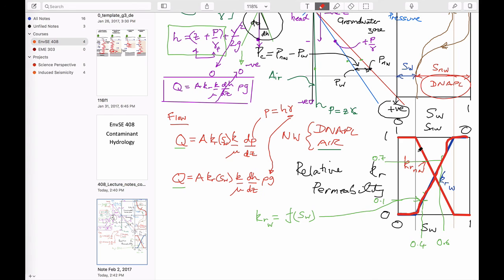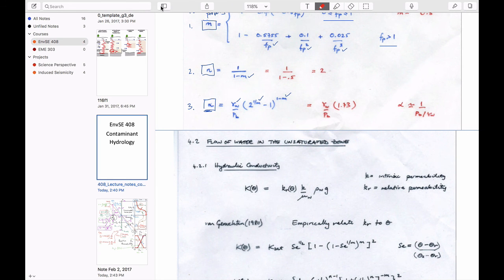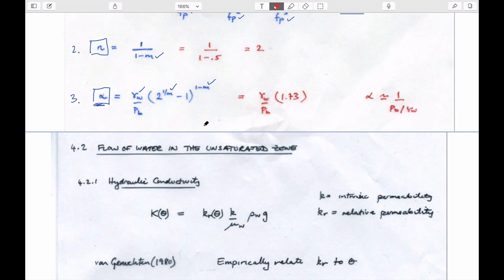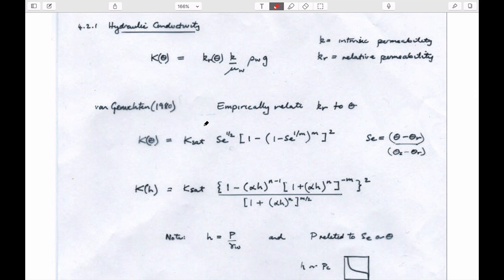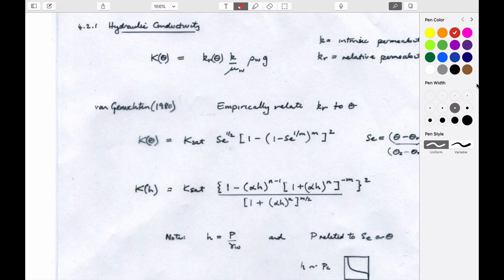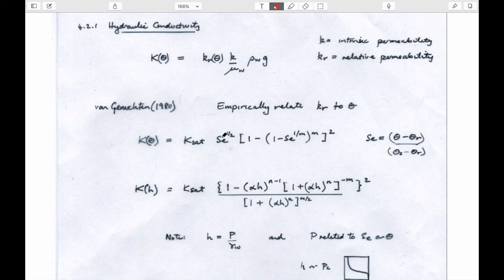for water. And so in the same way that we talked before about relating capillary pressure versus saturation curves and relative permeability curves to each other, we can do that using these relationships for Van Genuchten by using, again, this same kind of excruciating description of coefficients, but it allows us to be able to determine the magnitude of this term here, and that is this relative permeability term.